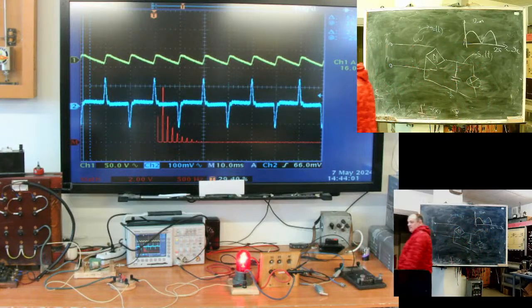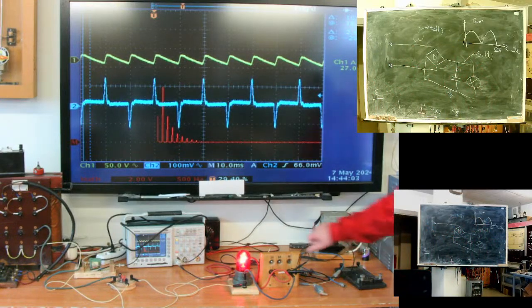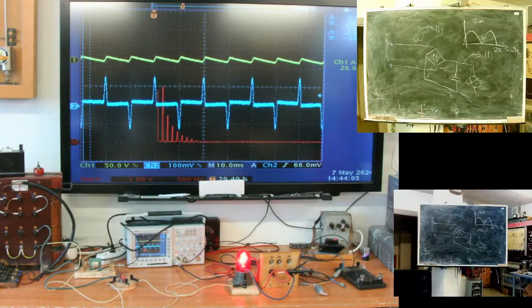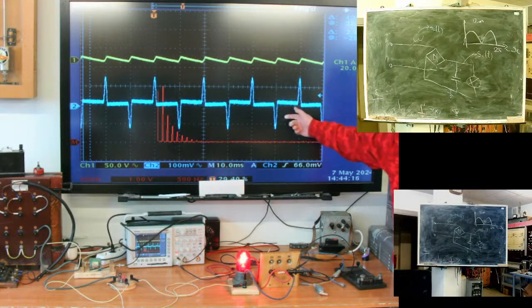So if you make that capacitor bigger, I can make it bigger. It will be better, because the ripples are too much there. More and more, finally it will be pure DC. Now the question with the blue line.